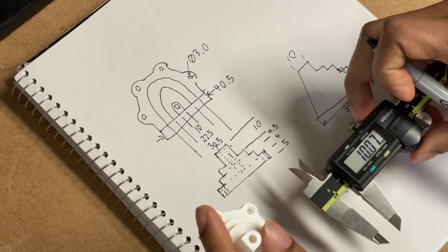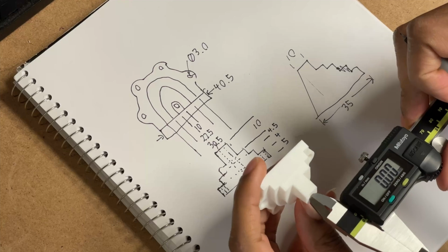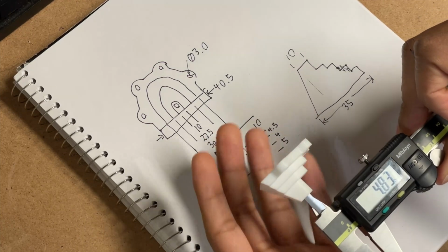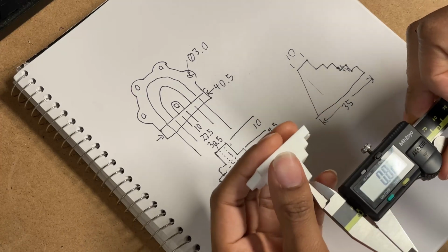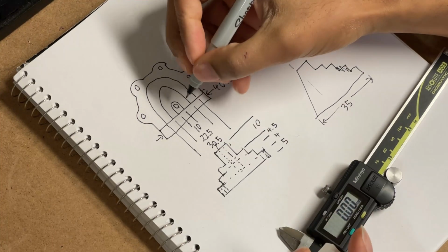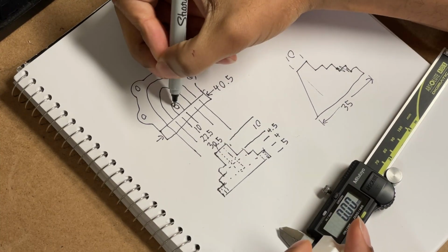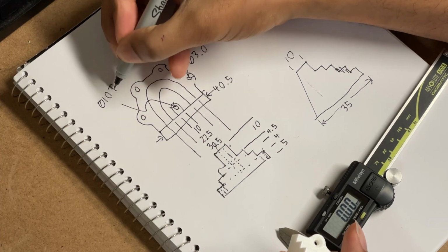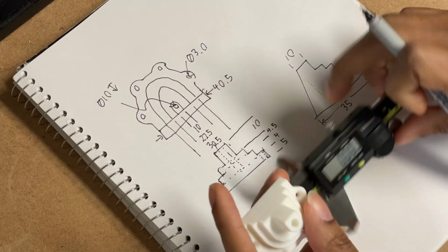Oh! What about the diameter of this hole? Well, use those inside jaws again. That looks like 4.5. Often I'll measure holes on 2 perpendicular measures. So this looks like a hole with diameter 10. But what about the depth? This is that blind hole. That's a symbol for depth, by the way.